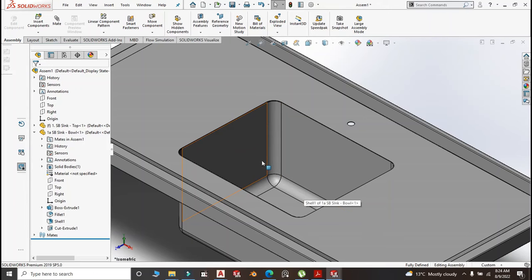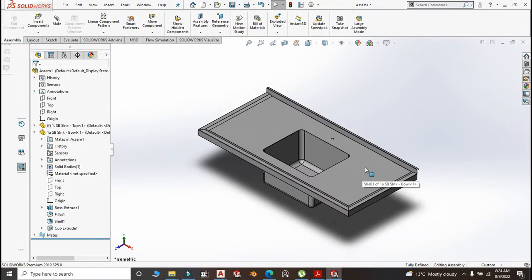First you balance the bowl to the cutout, do tack weld at one corner, then do another tack weld, tack weld, tack weld, then close tack welds all around before you do your full welding.